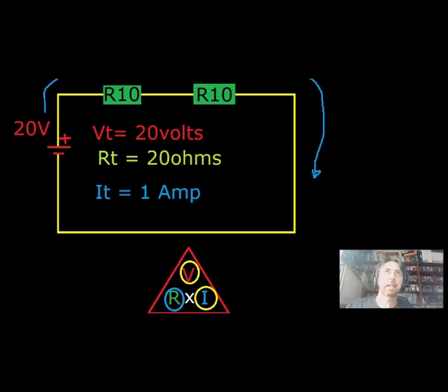Well, let's put that in there, makes sense. So that would be 10 volts there, and of course if it's 10 volts there, it's the same calculation, so it would be 10 volts there as well. So we know that there is 10 volts dropped equally here because the resistors are equal, so therefore the voltage drop is equal over each component, so 10 plus 10.